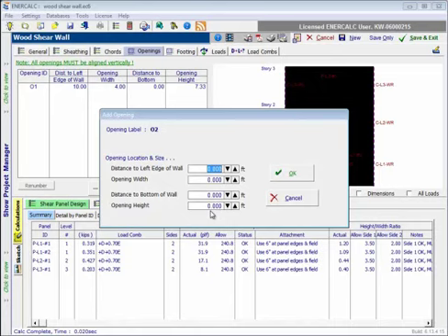Generally, your openings want to align vertically, kind of like a load-bearing wall type concept, and please do take a look at that section of the user's manual. Having said that, I do want my doors to align, so I'm going to provide the same distance that was 10 feet. The opening width wants to align, and there we can see evidence of an invalid opening. It thinks that it's not aligned yet, and that's just because we haven't fully populated the information for this opening yet. So it's checking as we go and giving us real-time feedback on the opening that we're defining.